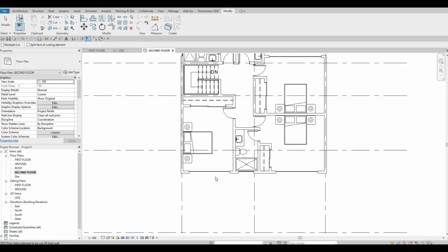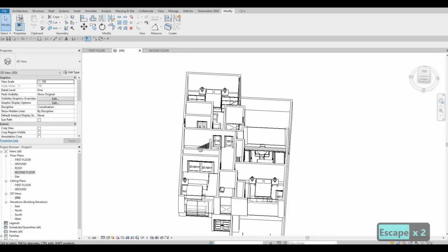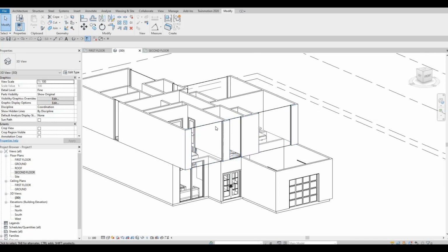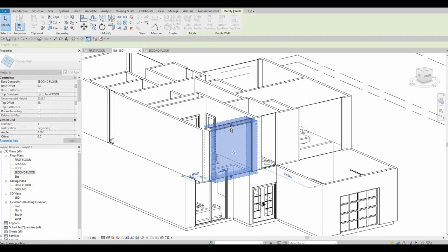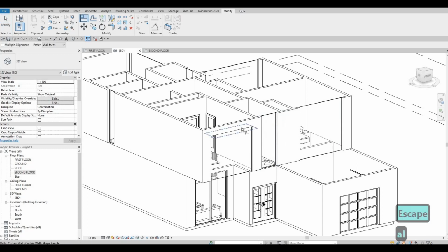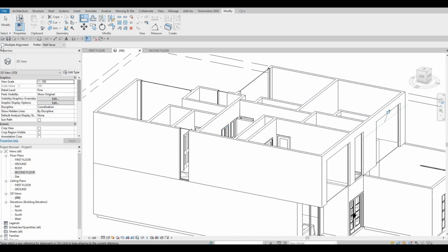So here, like that. And then let's go to 3D to change the height. Most of the time I put the same height. So I'm gonna pull down one, and then from there I will move everything on that height. So use align, so AL, select that height, and then here. Again, do it on the others. If you want to make this one same as all, you can check this one, and then you can just keep on selecting those. So I'm gonna do AL.